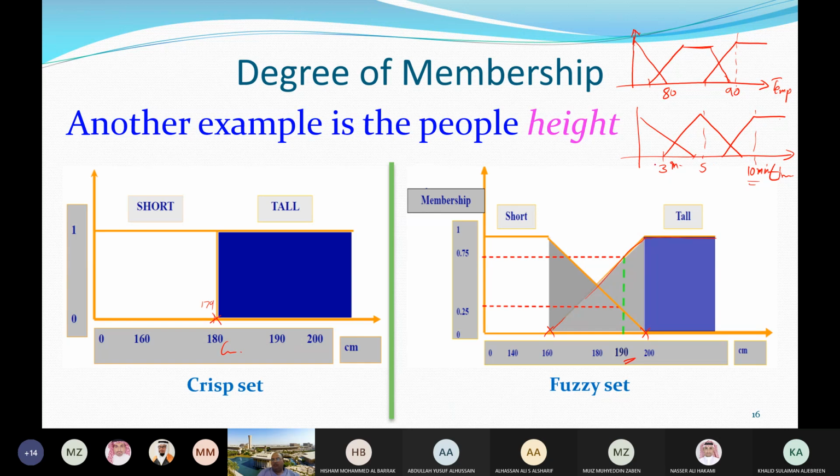Okay? If you have such a mechanism here, you can develop a 3 times 3, so 9 if-then rules. So when you say if the temperature is high, which is 90 degrees, and the time is long, greater than 10 minutes, then your action is trip. Your action is a signal goes to the circuit breaker to trip, or to isolate or to disconnect.